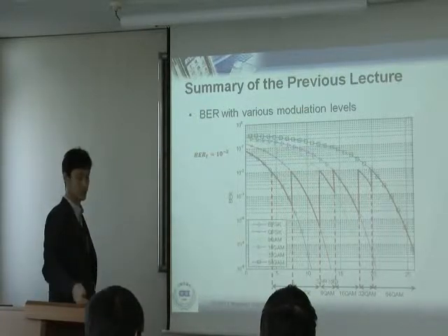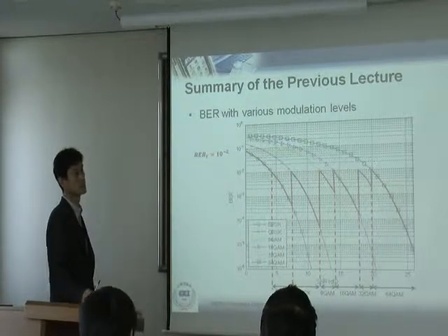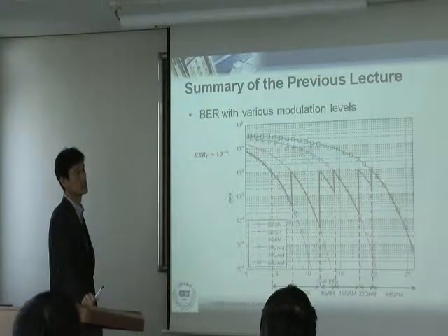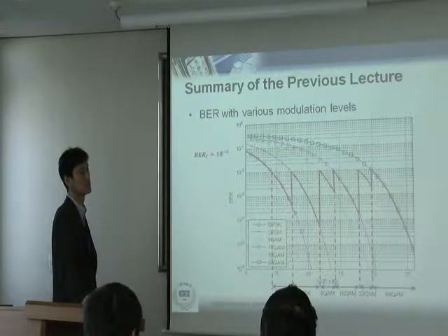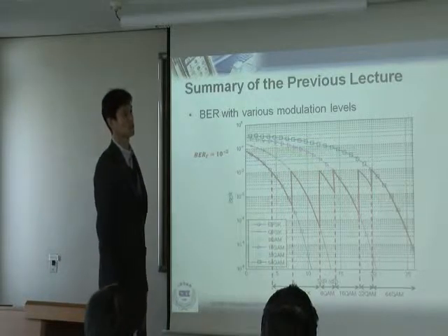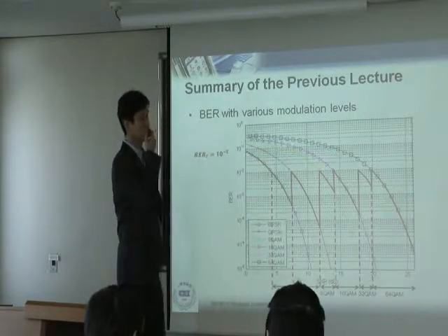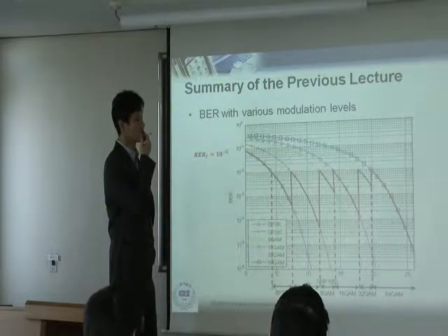If we take false decisions, the cost is again either a bit error rate, or in the reverse case we are spending more power. For example, if we should transmit in BPSK, and we are transmitting in QPSK, we are transmitting more power. So the cost is again the power.